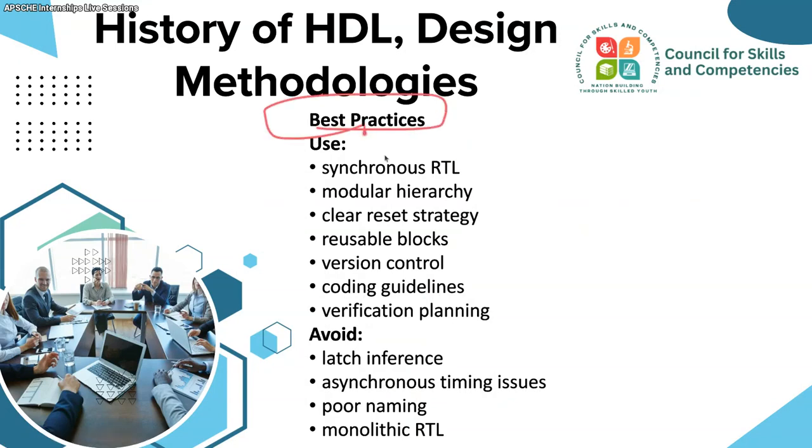Best practices: use synchronous register transfer logic, modular hierarchy, clear reset strategies, reusable blocks, version control, coding guidelines, and verification planning. Avoid latch inference, asynchronous timing issues, poor naming, and monolithic RTL.